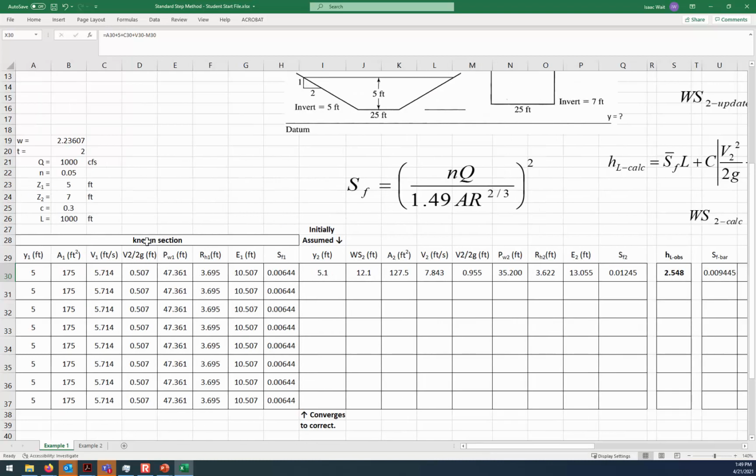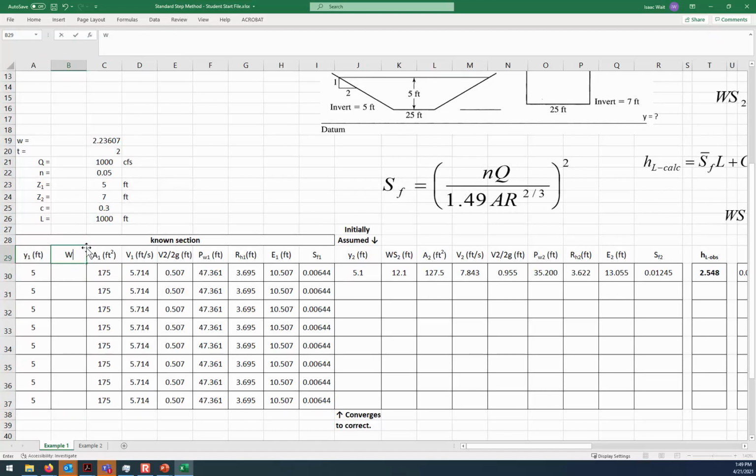Just to be sure, I am going to create a column that gives us the water surface. So let me insert this where we've got the water surface at 1. And that's going to have units of feet. And this will be the last thing. Since it's already 1:49, we're going to have to pause after calculating the water surface at 1. But it is the depth plus the elevation at location 1, and anchor the reference up to that.